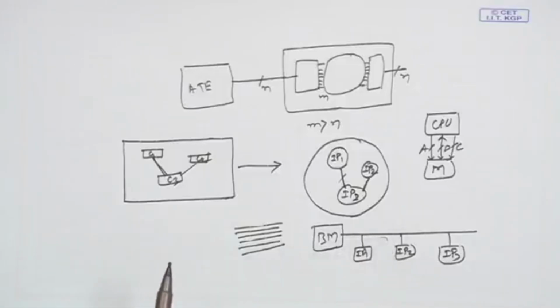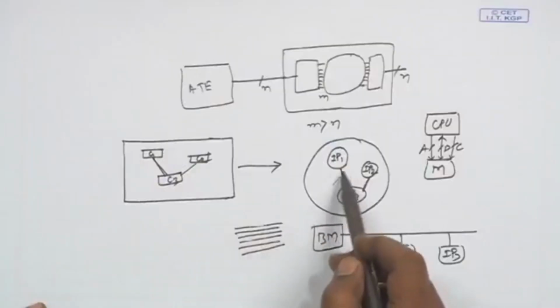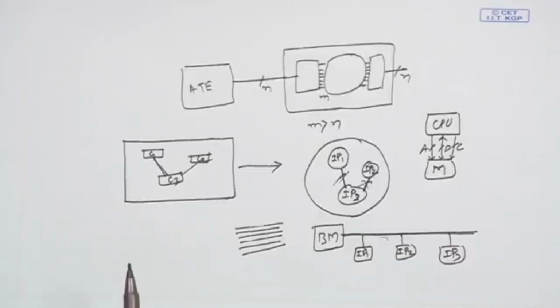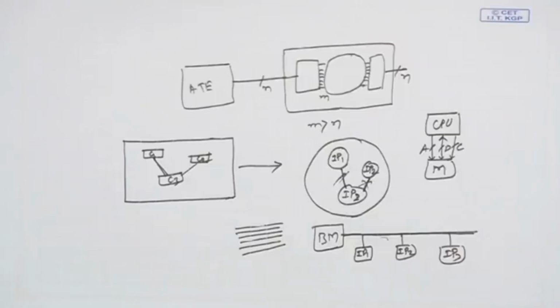The advantage is that we definitely save on the number of lines running throughout the chip, because all these lines will be replaced; everything will now happen over this bus, and the IPs need to communicate some sort of coded message through this bus for address, data and control. Say IP1 is CPU and IP2 is memory, they will do it this way. That makes the process regular, and we can have multiple levels of buses and all that, but at the same time this bus based communication has limitations.